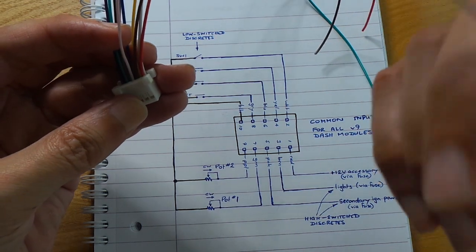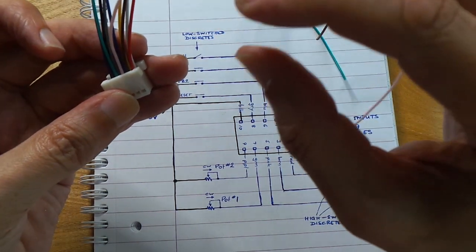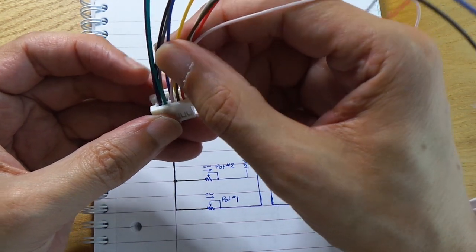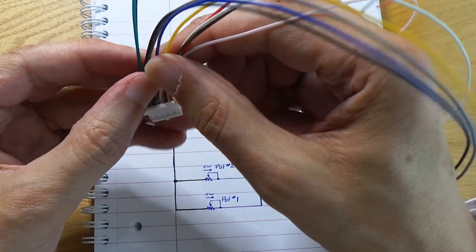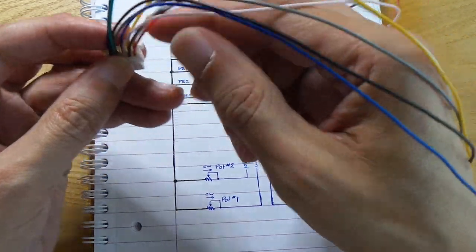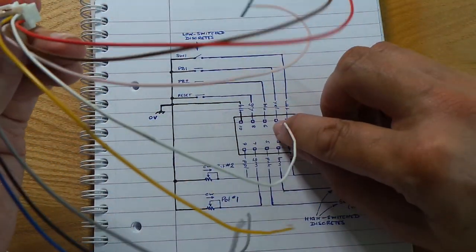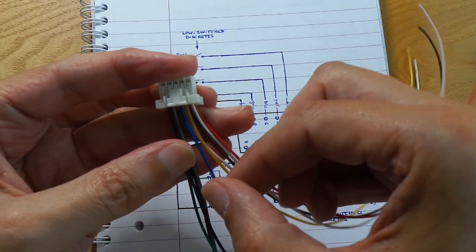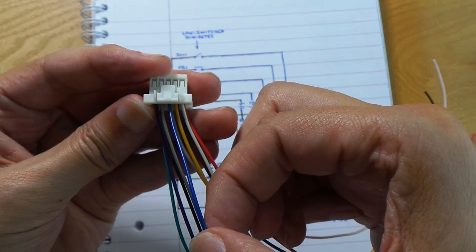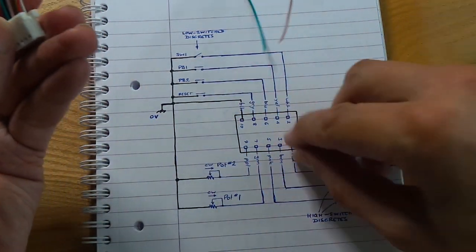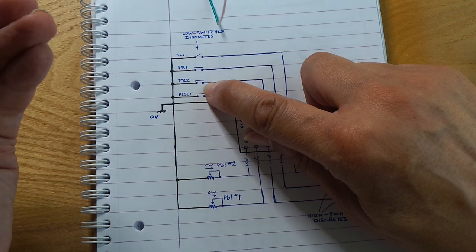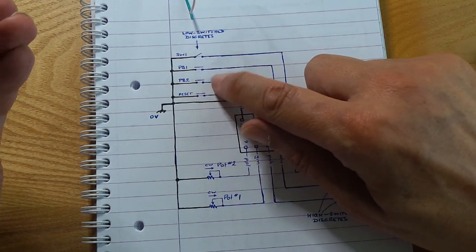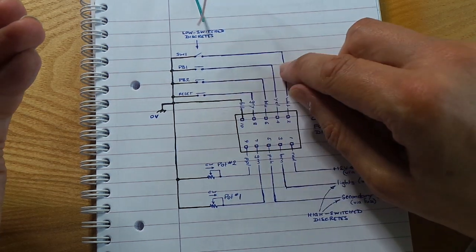So you don't have to connect that one, but it's useful, especially if you're using the dash module number 3 in its fully functional mode, where all of the side indicators and the dash top indicators have real functions. Pin 6 is going to be a blue wire, and that is this one right here, the middle one on the top row. And that is another ground switched input, this time to push button number 2. We'll talk about what these push buttons and the switches enable you to do later in the video.